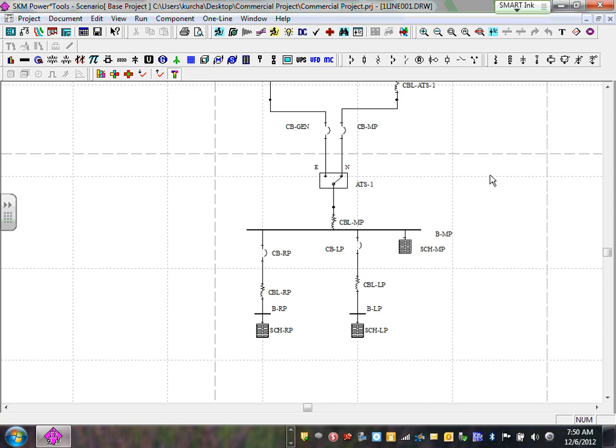So when you do the overcurrent coordination, guys, you're going to make sure that your circuit breaker does not trip every time you start the chiller. Here's the rule: typically, if you have a motor of 15 horsepower or larger, you do coordination for this motor. Anything less than 15, ignore. Can I have thumbs up, chat? Some people go down to 10, some people go up to 20, but 15 horsepower or less, ignore. More than 15 horsepower, do coordination on that.